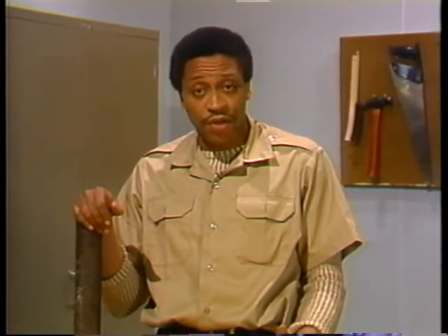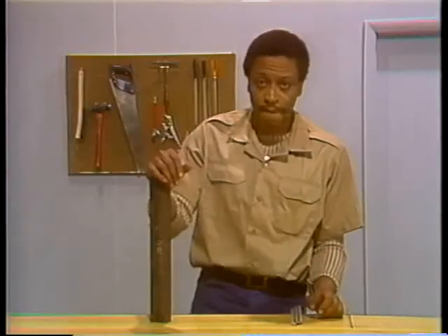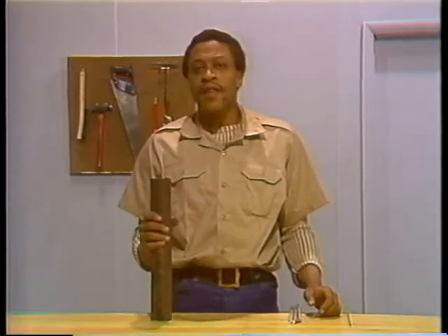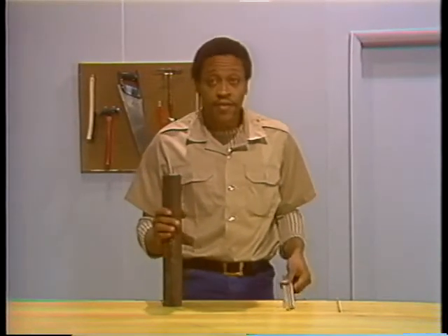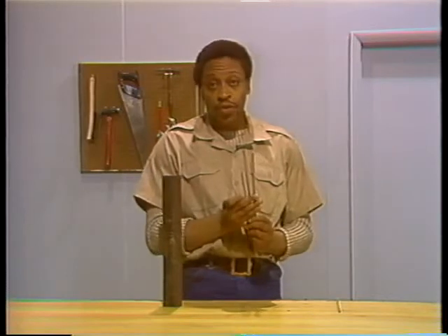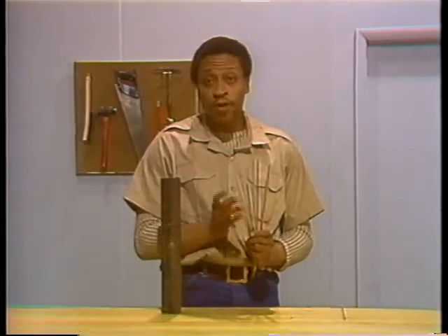If your plant has a written procedure, read it over carefully and be sure you understand it. If there are no written procedures, talk the process over with an experienced welder. Also, make sure that you know the materials, equipment, and working methods that apply specifically to your boiler. The type of metal that the tube to be repaired is made of and the type of weld rod used for the job are both important considerations.